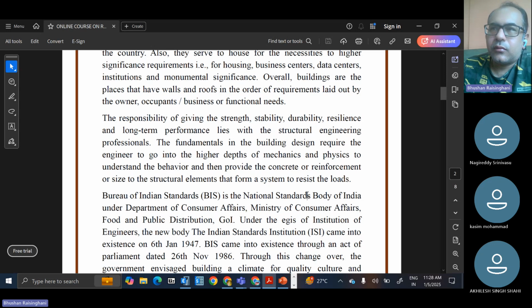So what happens if you are not providing reinforcement to create a rigid connection? The secondary beam will crack. So the overall rigidity or the integrity of the structure will get compromised, which you are not modeling in the software. In the software, you are only assuming moment is not transferred. However, whatever stiffness reduction has happened, you are not considering at the joints. So integrity becomes very difficult to consider in such cases.